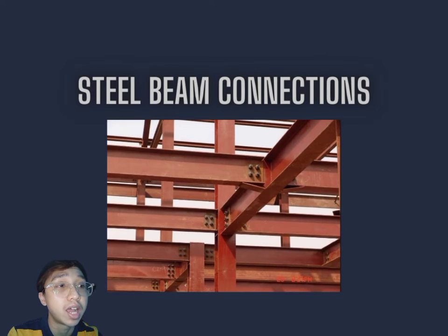There are various types of steel beam connections used in structures. Steel beam connections are categorized into two groups, namely framed and seated connections. In the framed steel beam connections, the beam is connected to the supporting steel element through fittings, whereas in the case of seated connections, the beam is positioned on a seat, similar to the case where a beam is placed on a masonry wall.